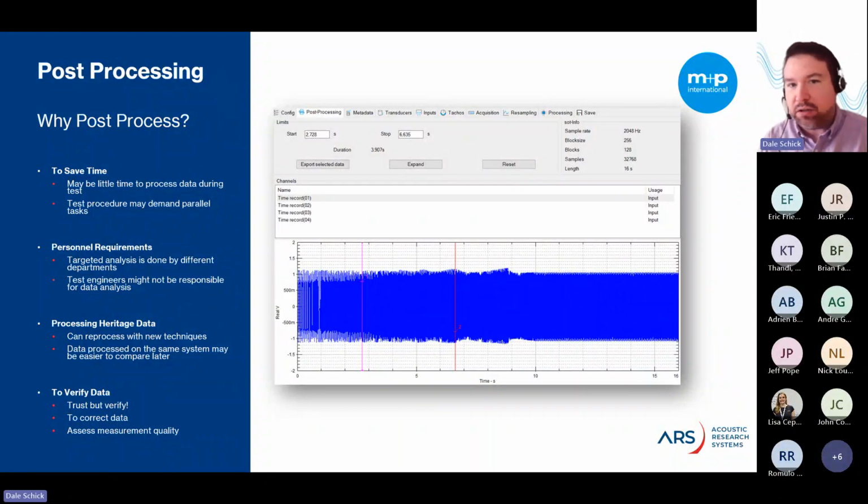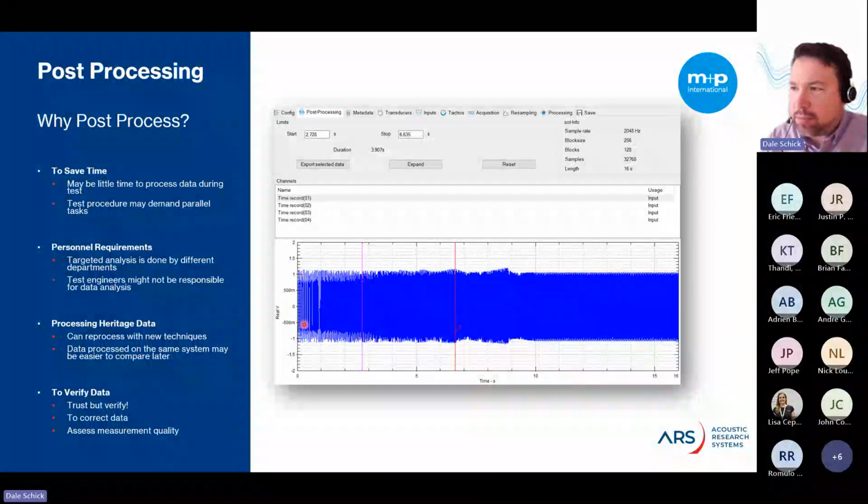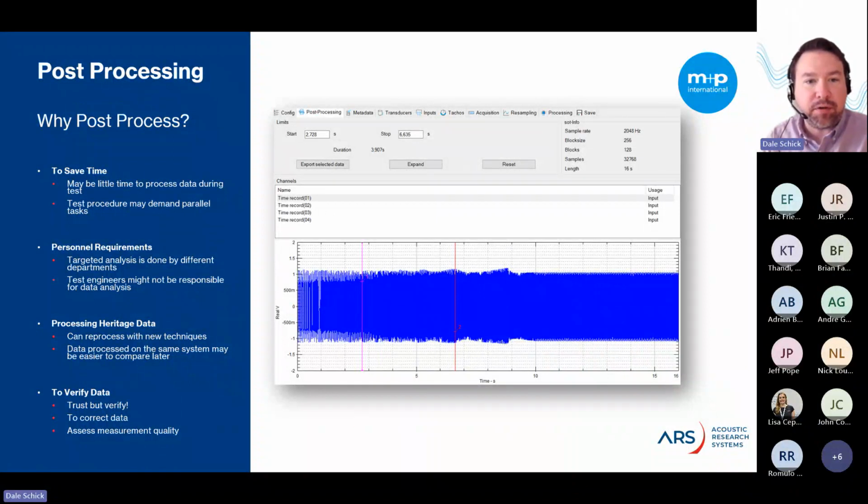This one's actually from rotating equipment, but it's just an example here. But essentially, the time domain data has seconds as the x-axis almost always. Could be milliseconds, could be nanoseconds, but seconds is usually the way it's defined. It has equidistant properties. So from one sample to the next, it's always the same distance, and that can help define the sample rate. And it usually has a peak value, right? So this one's in peak voltage, but you're typically recording in peak Pascal if you have microphones, or G if you have accelerometers.